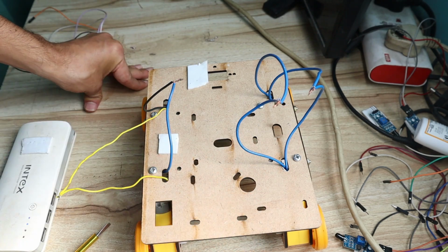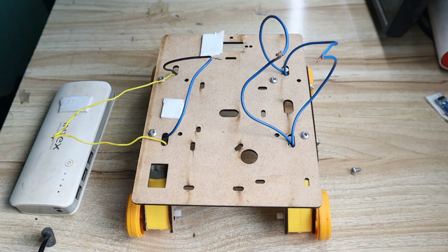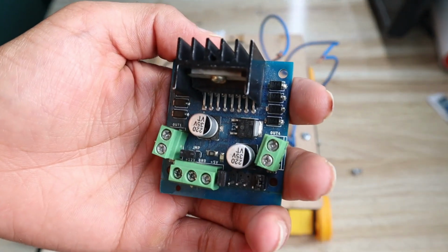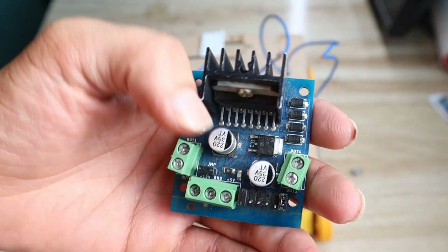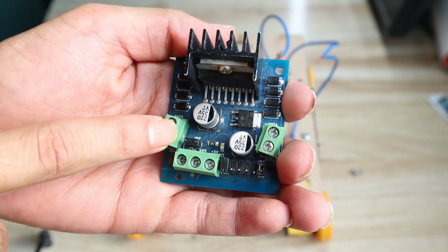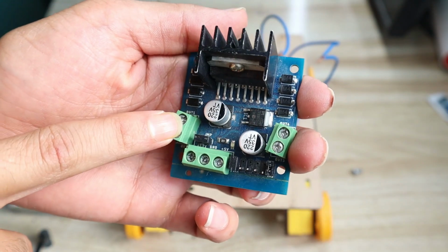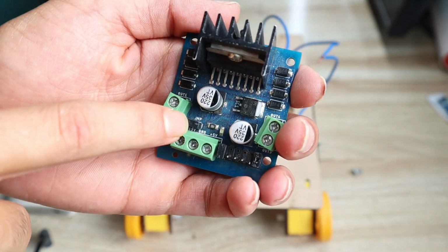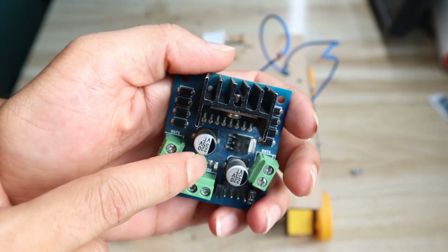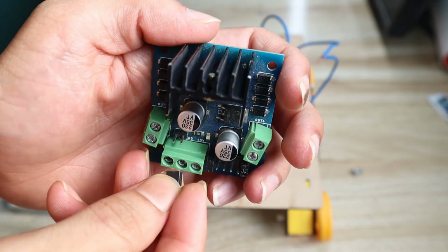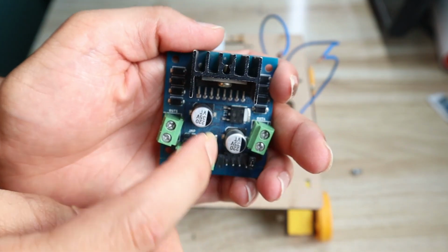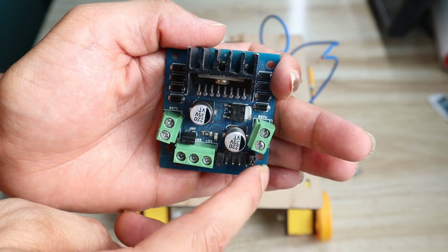Now these 4 pins should be connected to our L293D motor driver IC. Okay, first see the L293D motor driver IC connection. Each L293D motor driver IC has all these pins. Very important pins are this one. You can see here you should have the jumper. If you don't have the jumper, then your external power supply will not work. So verify here all the 3 jumpers should be there.